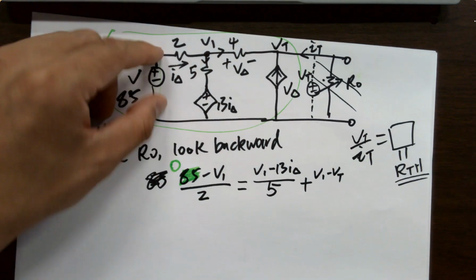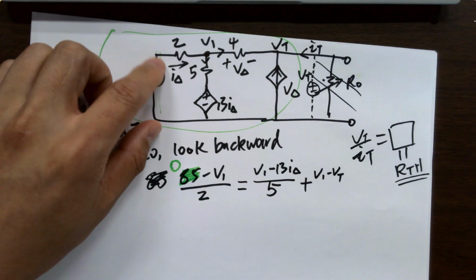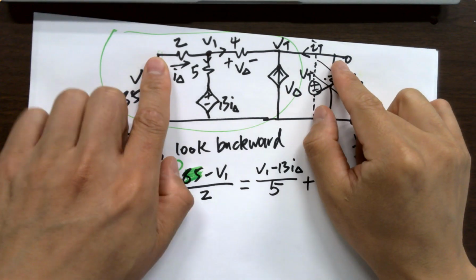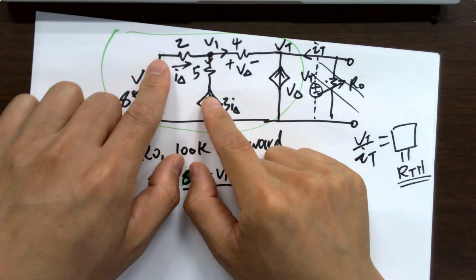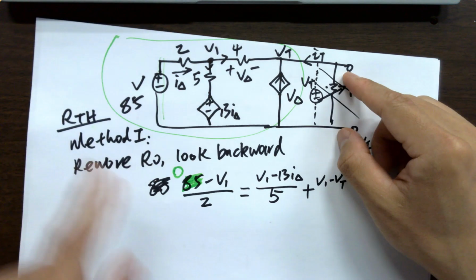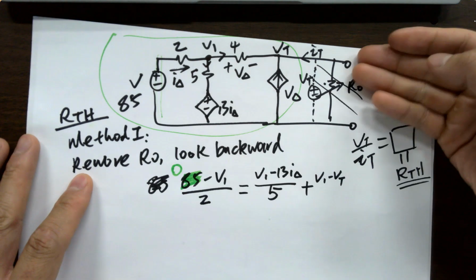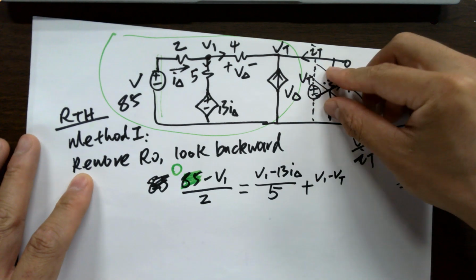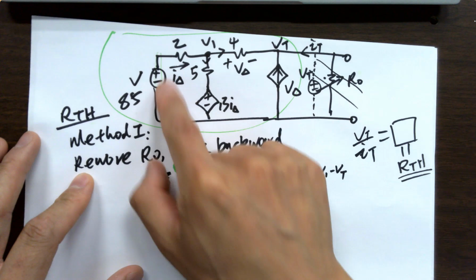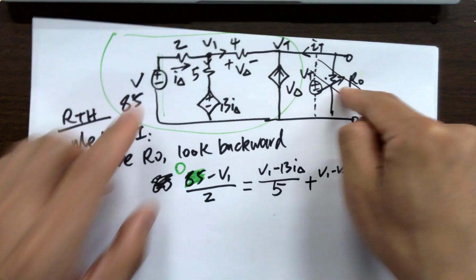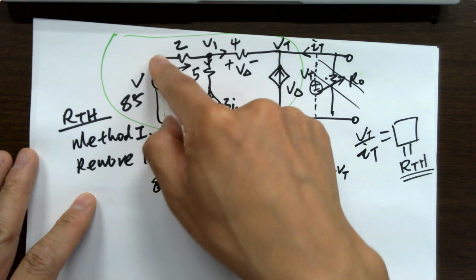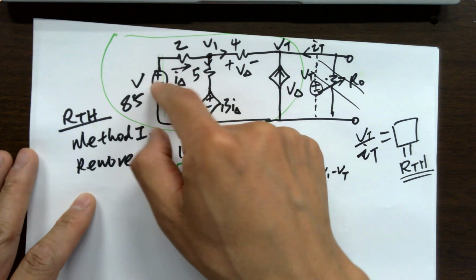You assume it's a short circuit because the internal resistance is super low. You are not calculating any voltages or currents or any combined effects from all the sources. What you are looking at right now is just resistance. If you have someone sitting here and looking backwards, this one from the person's perspective is just 0 volts, just a wire.